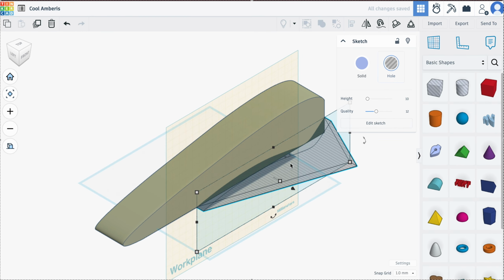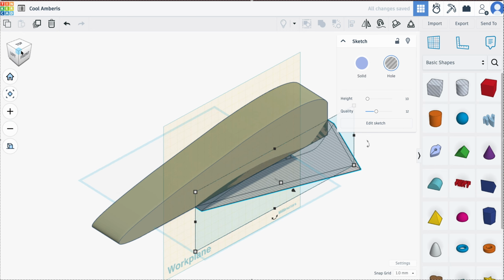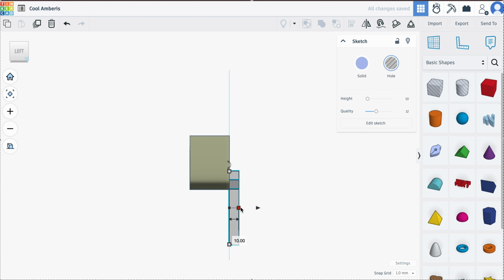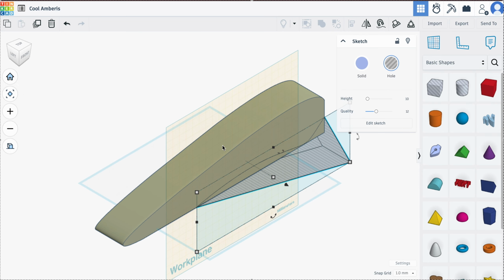I want it to be the whole shape again. I'm going to go 2D view, looking at it from the front or from the left. And I'm going to pull it again all the way through. So if I just type in -42, it will make it go the opposite way. Because if positive is that way, minus is that way. It's a 42mm thick piece of timber.